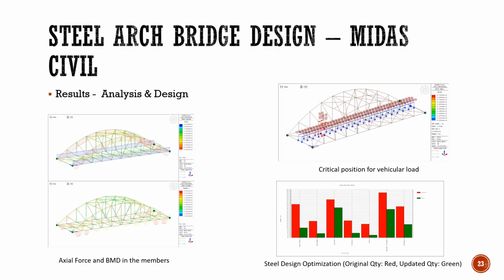To summarize, we have modeled a steel arch bridge, analyzed it and designed it in MIDAS Civil. After that, we took a joint where several members were coming. We exported that joint to FEA NX and remodeled it so that analysis can be performed, and we have checked the stresses at the interior and the maximum stress in the joint so that the gusset plates can be optimized based on the stresses obtained.